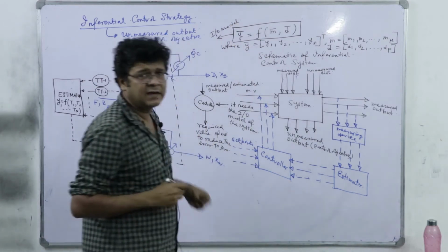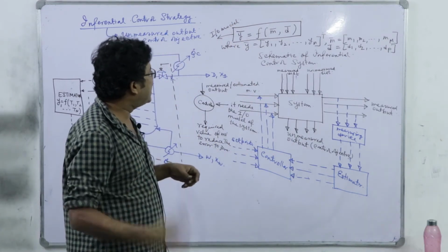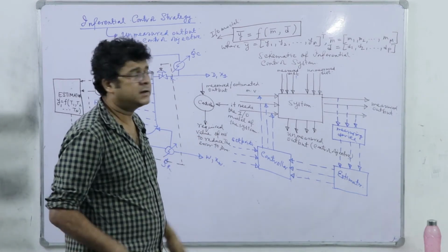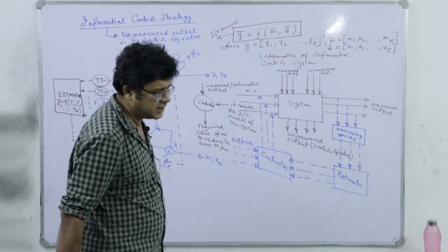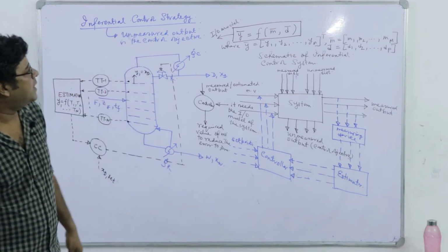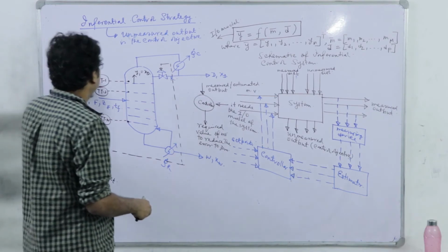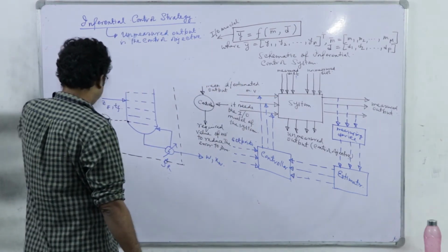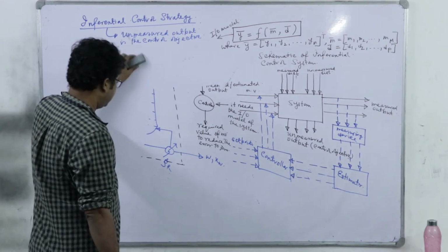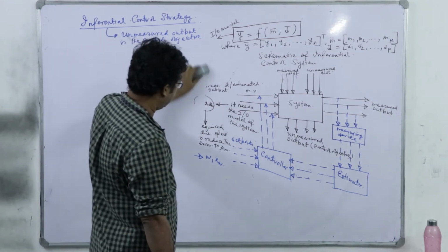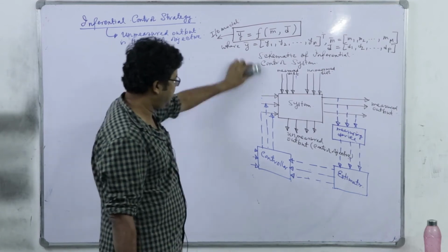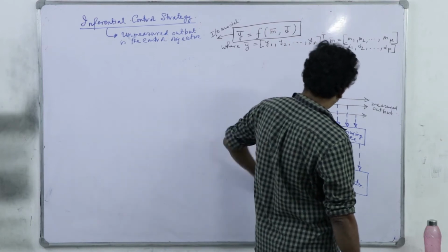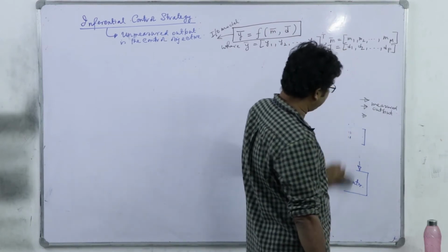Now, how to derive this input output model? We have to formulate the state model of that system, in the form of certain differential equations. There it will not be this sort of algebraic functionality, but rather it will include derivative and integral operators, and will be called the state model. I will give you an example.